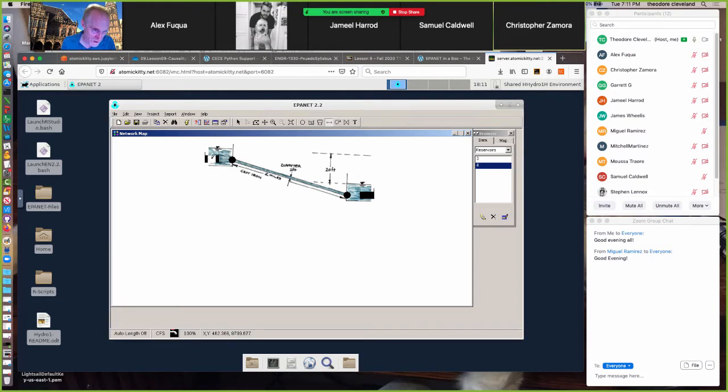So we have to use our hydraulic knowledge in order to produce the kind of system that we want. By putting these short, large diameter pipes in, essentially we're producing zero head loss connections to the nodes from each of the reservoirs. So it's as if that node is actually in the reservoir. That would be a good mental model. And now we will connect the two nodes with a cast iron pipe.